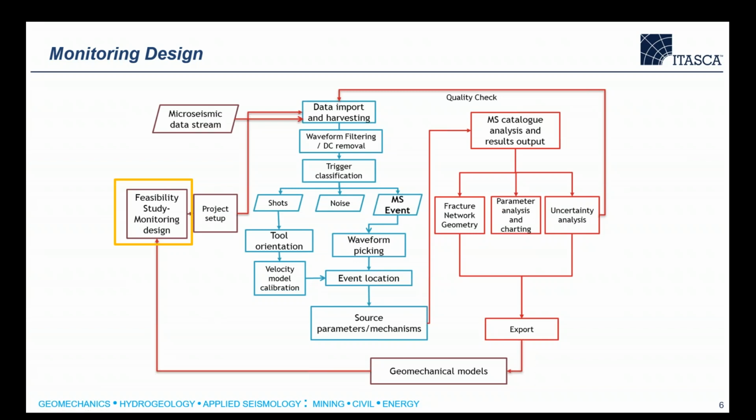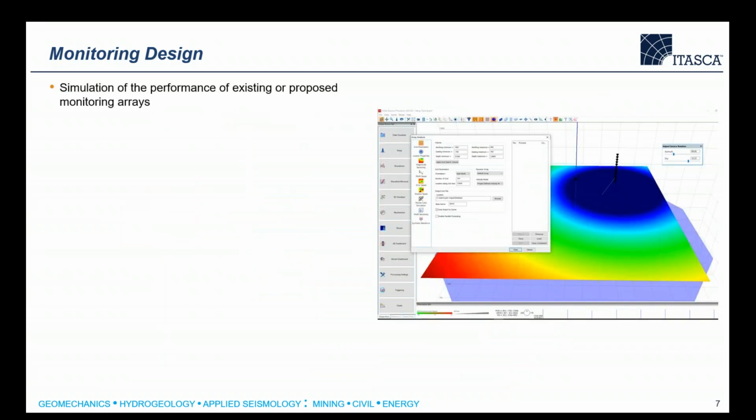If we have the flexibility to position our tools, our stations, in different positions around our volume, our objective, then InSite has the tools to perform an optimization of which position for these tools will give us the optimal coverage for our objectives. And it's basically the software, what it does, it runs a simulation.